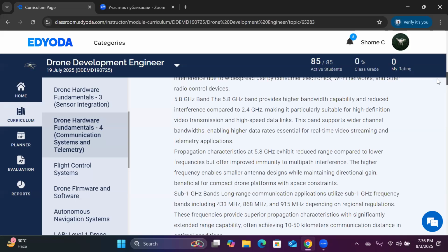That is why the communication box is connected with a motor. Whenever a directional antenna is used, or in any kind of flight motion, from the initial start, your communication box is connected with a motor, and automatically it will adjust or calibrate with the orientation of the UAV. And after that calibration is done, it automatically gets fixed to a particular direction. After that, you cannot touch the communication box. If you touch the communication box after the calibration is done with the motor, then the data will all get lost, or you will get garbage data on the reception side. Okay.